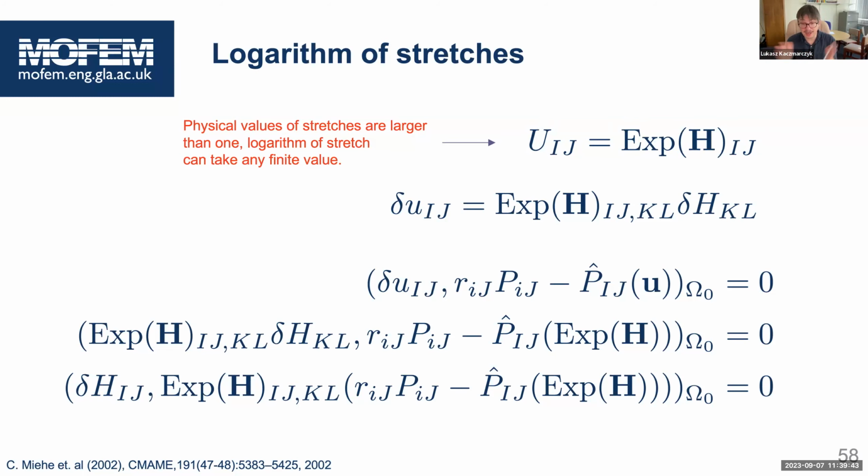So there is some barrier in every physically proper, accurate constitutive equation that prevents the stretch from becoming zero. That is typically realized by some logarithmic barrier function. For example, the Kirchhoff-Saint Venant material is not a proper constitutive material because it will not prevent interpenetration.